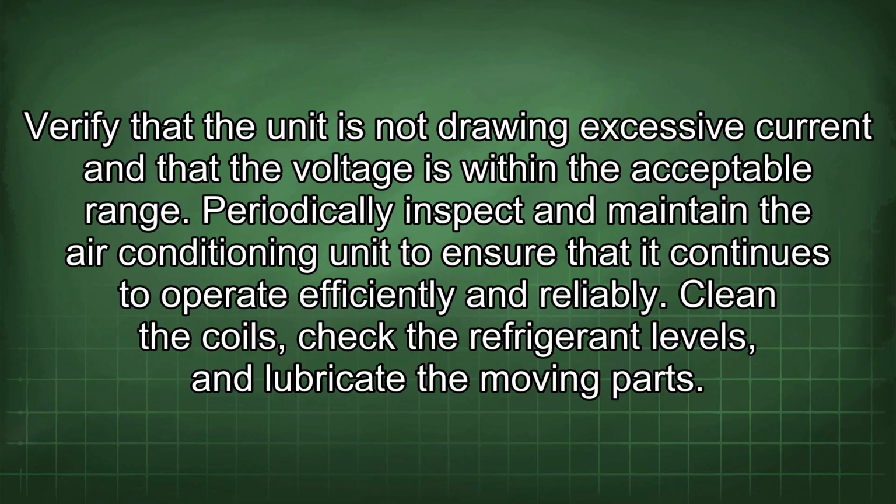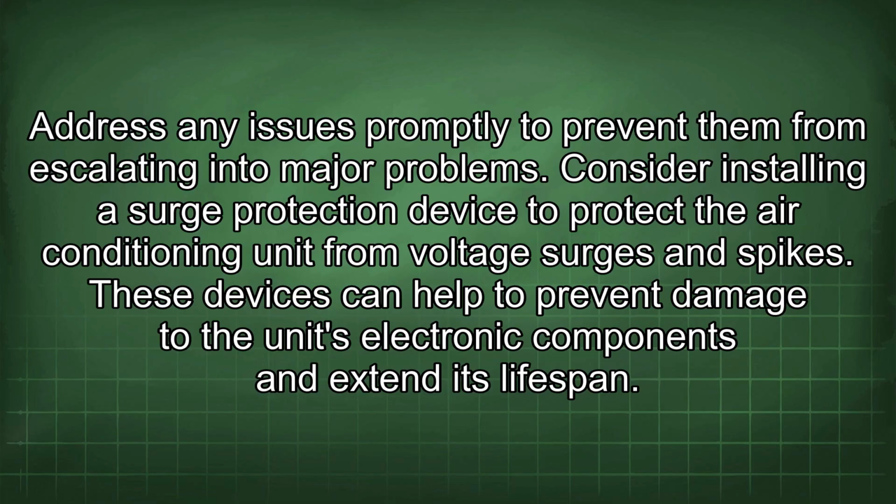Periodically inspect and maintain the air conditioning unit to ensure that it continues to operate efficiently and reliably. Clean the coils, check the refrigerant levels, and lubricate the moving parts. Address any issues promptly to prevent them from escalating into major problems.